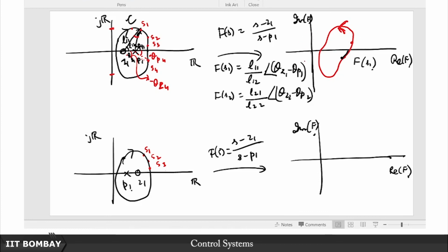And so the question of this encirclement doesn't even arise in this case, right. In order to see this more transparently, just see what this difference in angle is after all. You concentrate on this figure here, you see this is the external angle and this is the sum of interior opposite angles. So the difference between these angles, that is the pole and the zero, is something similar to what we did for the phase lag-lead compensators, right. So this is the net phase contributed, you see.